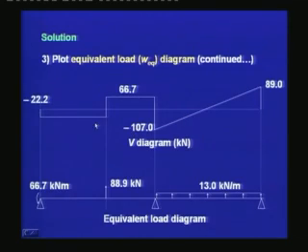Thus, given the shear diagram, we are able to calculate the equivalent load diagram due to the prestressing force. It has a point load where the CGS has a sharp bend at D, and it has a distributed load where the CGS has a parabolic variation in the span BC.